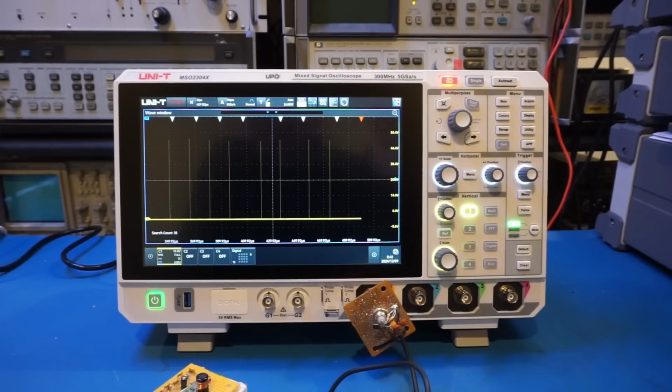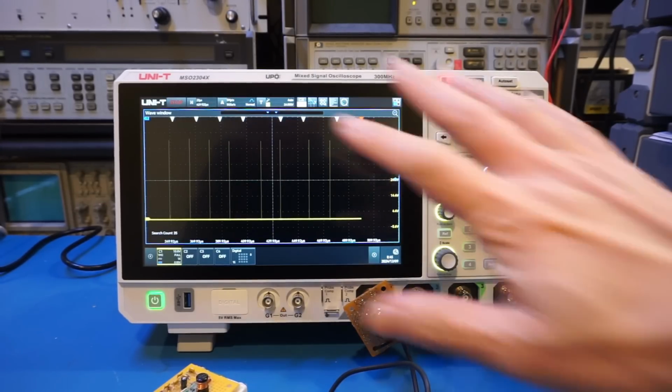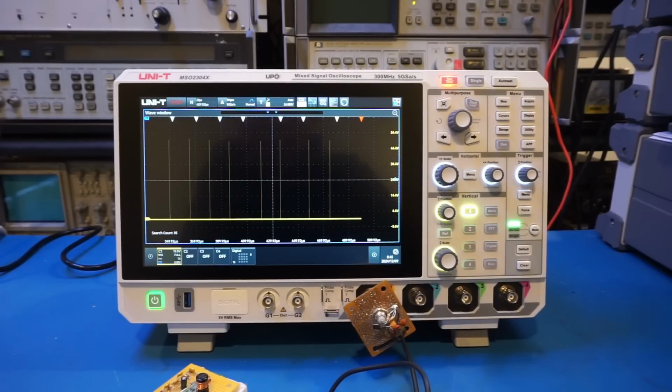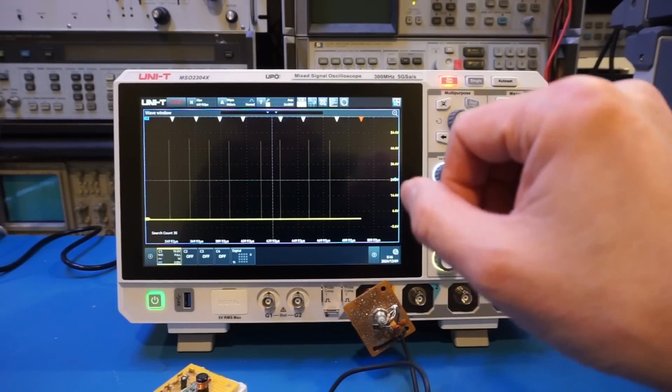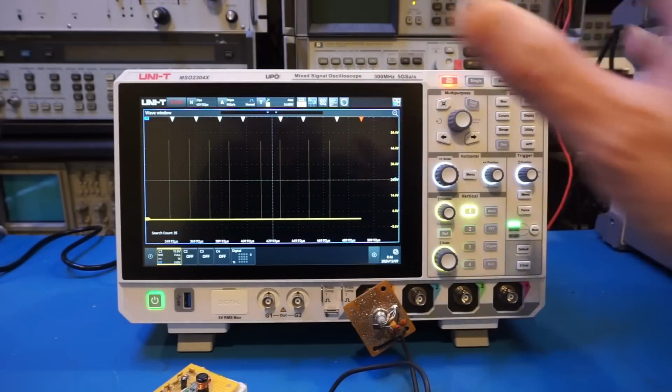The concept of segmented memory is fairly easy to understand. By dividing the sample memory into smaller segments, when triggered, the oscilloscope will fill the next available memory segment, and once the segment is filled, the oscilloscope will stop capturing data and rearm the trigger and wait for the next trigger event to occur. So even if the trigger events are few and far in between, like what we have seen here, you are guaranteed to capture all these rare events. And because each memory segment is operating essentially independently, you are not going to waste all this space, because once a memory segment is filled, the capture is stopped.